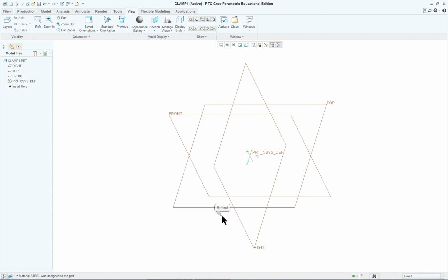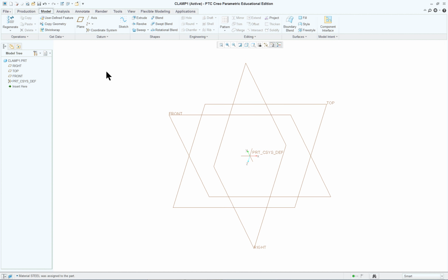Okay, close. And we're going to do something a little bit different. Many systems require you to have your sketch done and then you do your feature. We've been doing the feature first and then doing the sketch internally, which personally I think is better because it's embedded. In this case though, we're going to actually create an external sketch. Now don't get in the habit of doing this. Do whatever the book tells you to do. Don't decide to use external sketches from now on throughout the book, because that's not what it's telling you to do. If you need an external sketch and you're going to use that sketch in other features, that is the reason for having it separate from the actual command. In this case, the feature of the part, which is the solid.